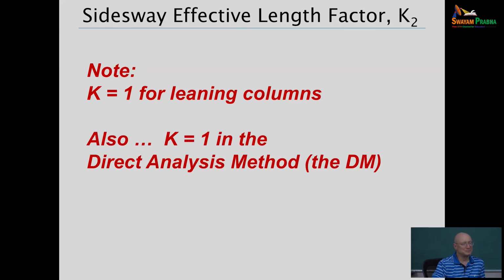So why would we want to? Let's say you've got a structure and you don't want a bracing diagonal going through your doorway, or you need access. Yeah, a moment frame would be a sway frame. That's correct. It's obvious it's always going to be more efficient if you can have walls or bracing systems in the frame. But in some situations, we want to use a moment frame.